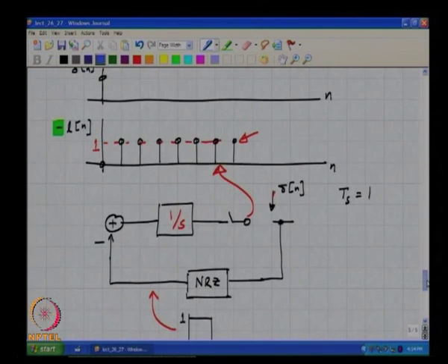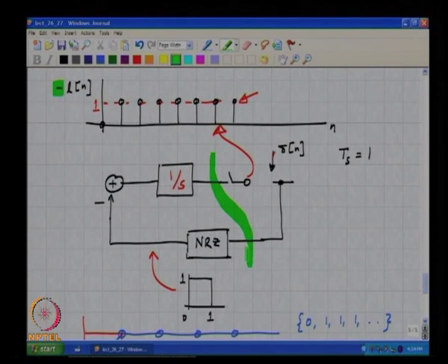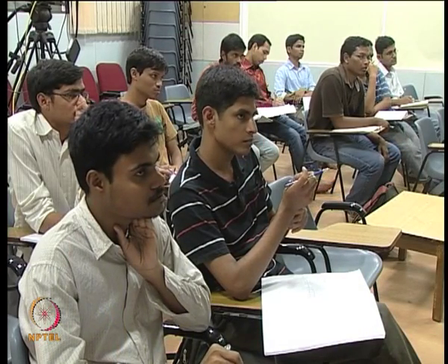So, in other words, this part here, where the input is a discrete time sequence and the output is also a discrete time sequence, is completely indistinguishable from the situation where we had a truly discrete time filter which directly processed the input sequence without having any continuous time circuit, right, which means that an integrator which is being driven by an NRZ DAC is mimicking the role of a discrete time integrator. All right, is this clear?